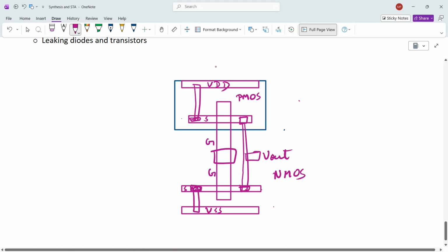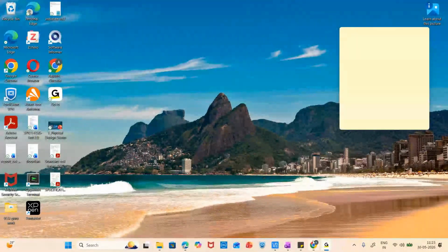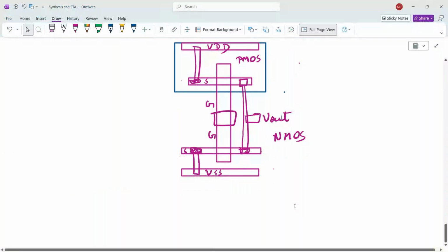When you give this to your foundry, only then will it understand. This is given by the layout team. They will characterize the individual cells and give them to us. That is what all the information present in our input files is. Using those input files and all the libraries, we take the cells, we connect them, we connect the signal, the clock, and the power, and we make sure it is working at the given frequency. Then we give that GDS2 file to the foundry.